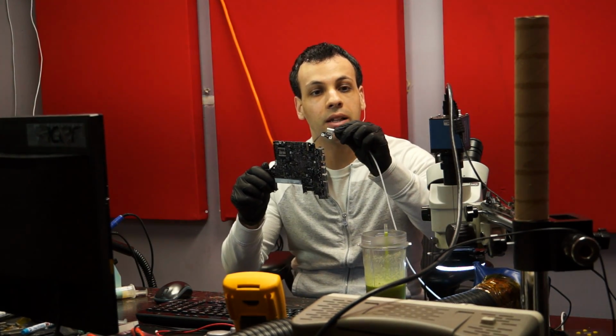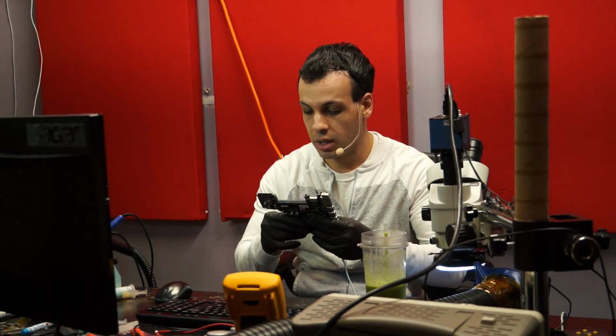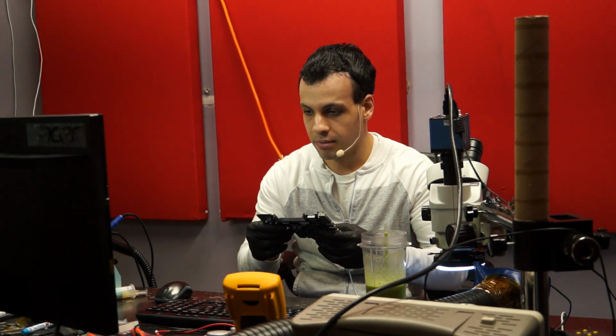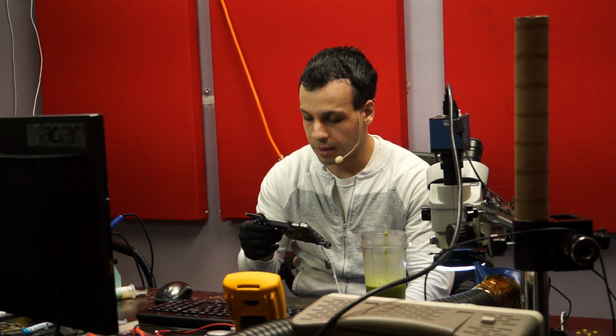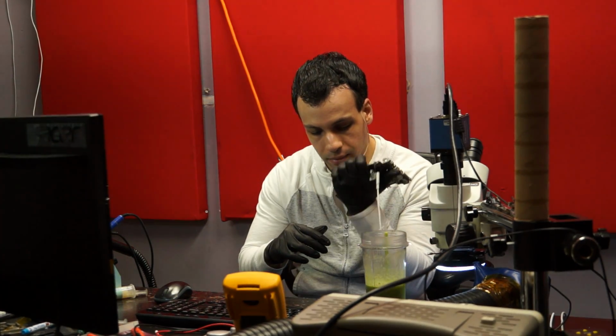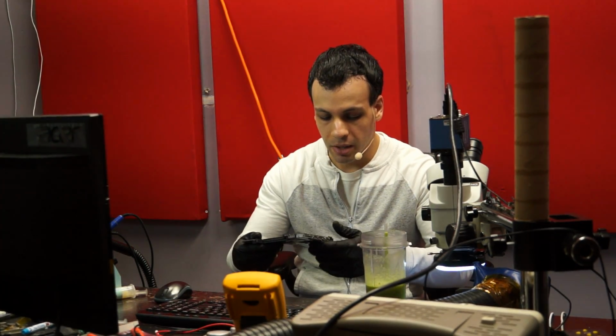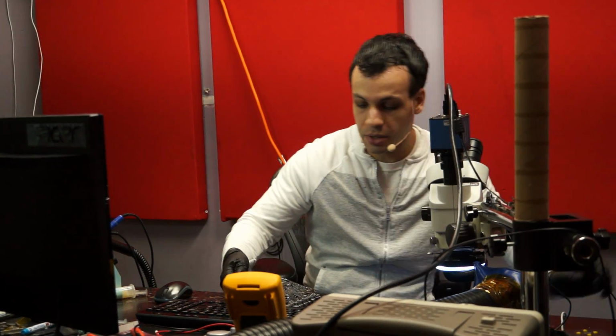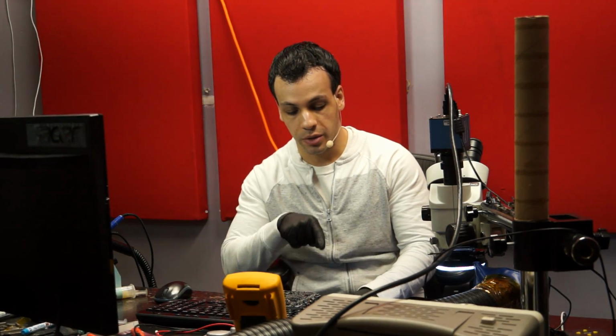So we have a green light in the charger. The green light in the charger tells me that I'm burning my finger here. Great. Oh, the board is telling me what's going on with it already. Anyway, so we have a green light in the charger. It means PP3V42 is present. If you watch my one-wire circuit videos, you'll know why that is. We need 3.42 volts for the one-wire circuit to function and for the green light to turn on.